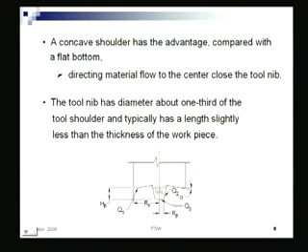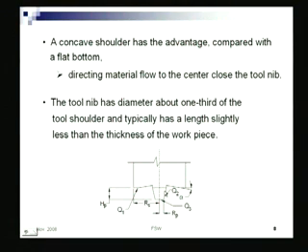What will decide this diameter? If the diameter is too small, it has too little strength. So the translational force, it won't be able to withstand, it may break off. If it is too big, too much translational force is necessary, that also may not be good, right. So these are the aspects which are to be looked into while deciding what should be the diameter of this.